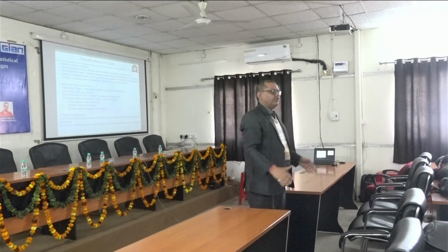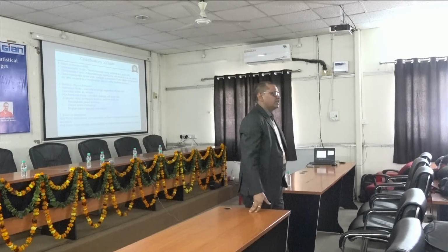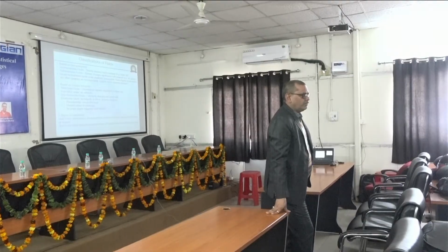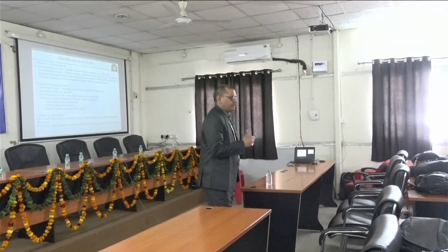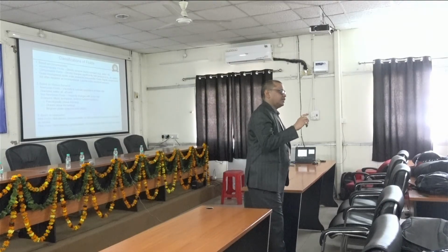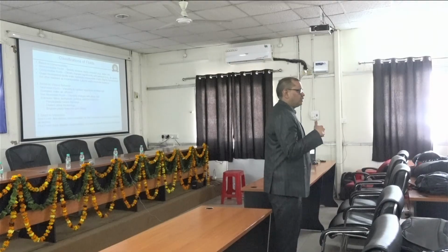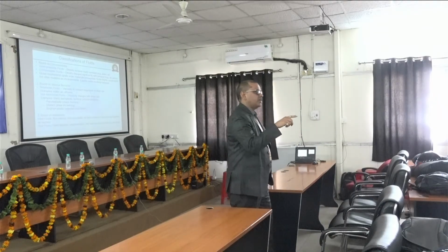So that type of fluid is known as a viscous fluid, and Newton's law of viscosity states that stress is directly proportional to the rate of deformation. And if stress is directly proportional to the rate of deformation, then as per the mathematics, in a relation of proportionality another constant will come. And when a constant comes, in physics it will be some physical parameter.